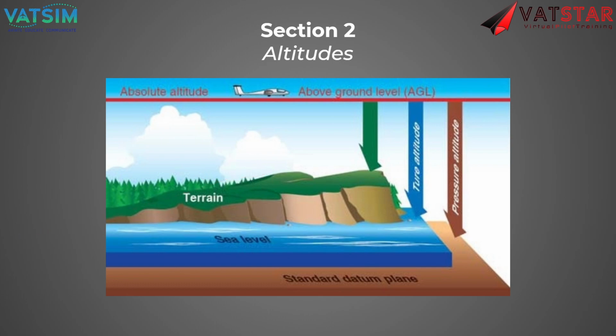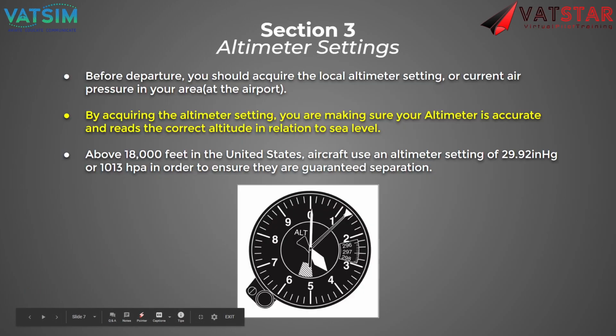Does that kind of make sense to everybody? Yes. So you don't have to worry about pressure altitude too much. You're really going to be concerned about your true altitude or indicated altitude, because that's what air traffic control is going to have you use.